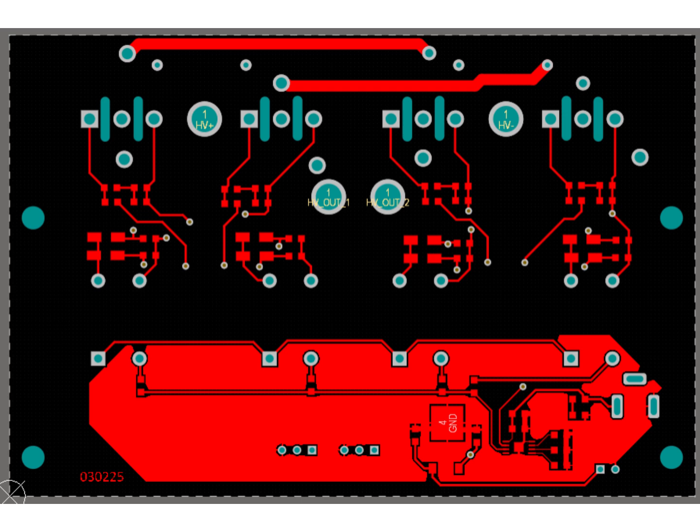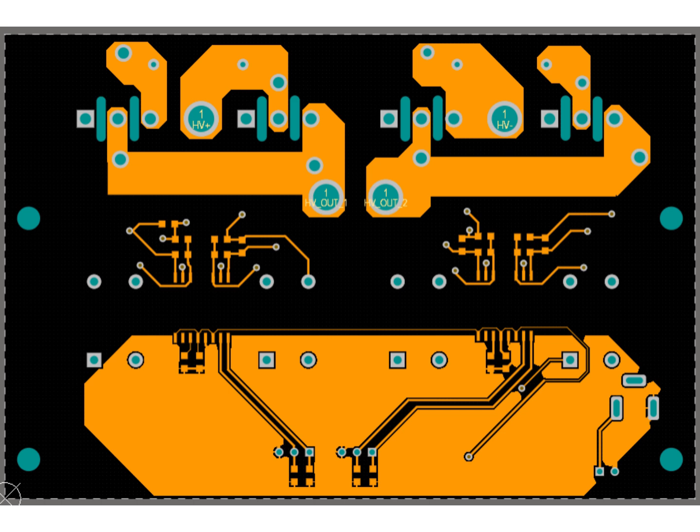Short and compact current loops. Clear separation of power and control sections. Proper creepage and clearance for a 400-volt DC bus. Clean, low-inductance gate drive routing. Good thermal and mechanical integration.